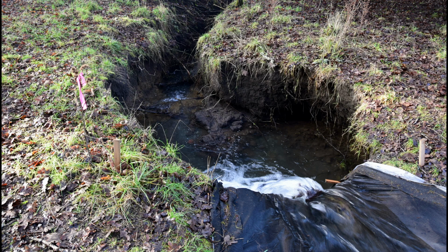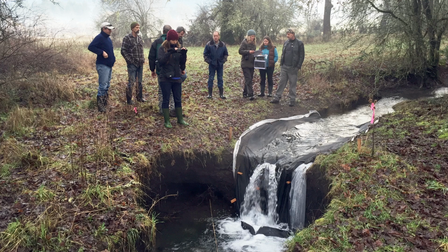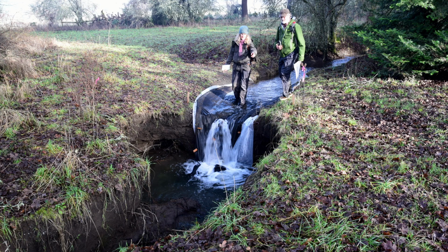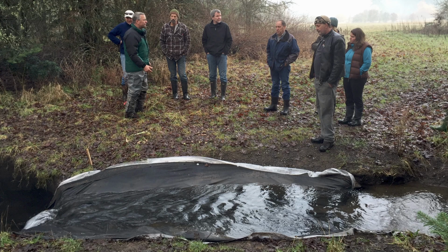It's very tempting to try inexpensive ways to control head cuts instead of paying for rock. Here's where plastic was placed over a head cut in an attempt to stop the erosion. Water flowing over the plastic has carved a deep pool at the base of the head cut. This deep pool will soon undermine the plastic and allow the head cut to continue upstream. Notice that the flow of water has been deflected and it's now eroding a much wider head cut on either side of the channel. I've found that it's not possible to control a head cut by using plastic or geotextile.